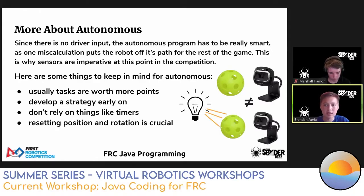When you're doing this, you don't want to rely on things like timers or battery level, or even like the color of light in the room. I know I've neglected this rule before, and when the battery gets a little bit low, then the motors and servo motors don't work the way they should, or the way that has been tested and proven to work, and then everything goes wrong. Or the color of the lights in the room change, then your color sensors and your cameras are giving improper data, and in match that can mess up the routine.